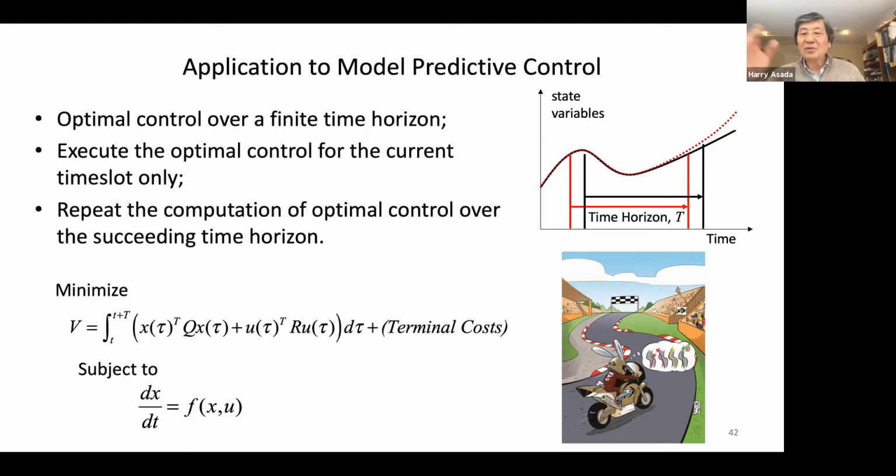But I know that u(t) is basically good, the part of the optimization here is consistent with the future best trajectory. So we executed that one. And then at the next time step, we set the time horizon for the next capital T, recompute this again, and execute the first optimal control u(t) at that time. And then we cycle through this forever. So we don't care about the future trend over here, but we focus on some meaningful time horizon and solve this repeatedly.